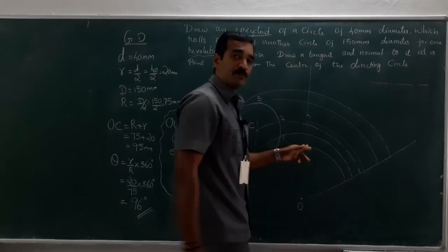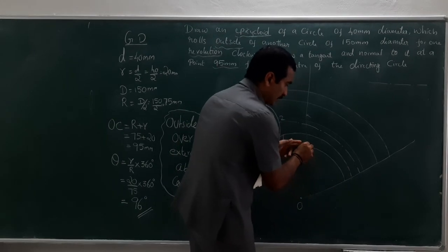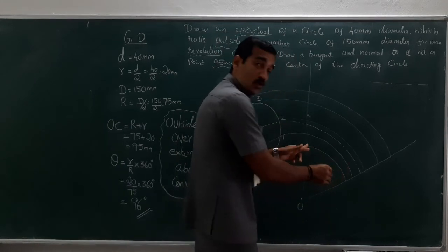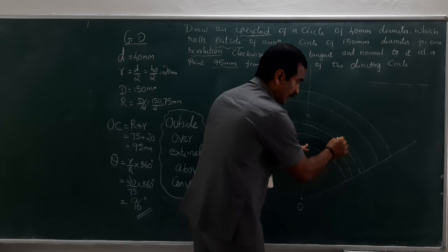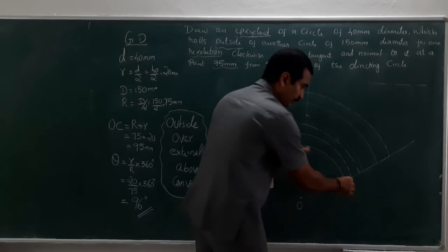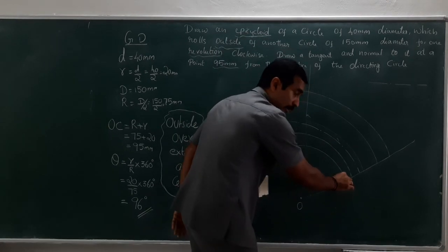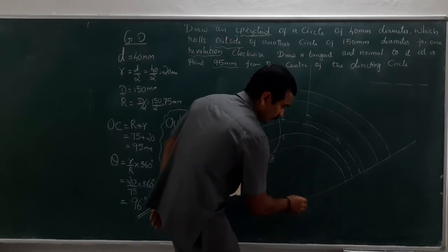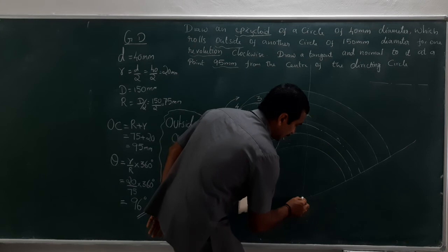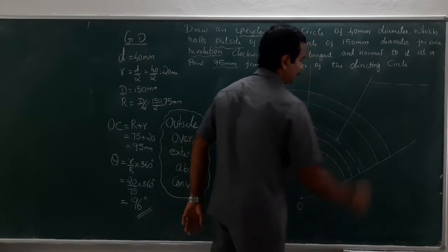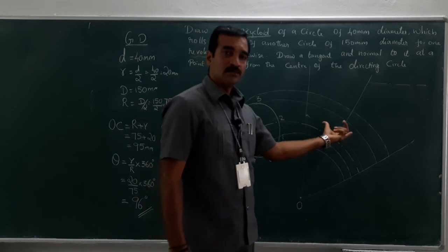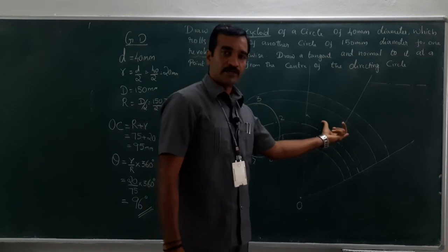These are 2 extreme points. Keeping the compass at this point, stretching out, taking more than half, cut an arc here. Similarly, keeping the compass at this extreme point, cut an arc here. Now draw a line from O passing through this intersection. Look at here. I have split this into 2 equal divisions.